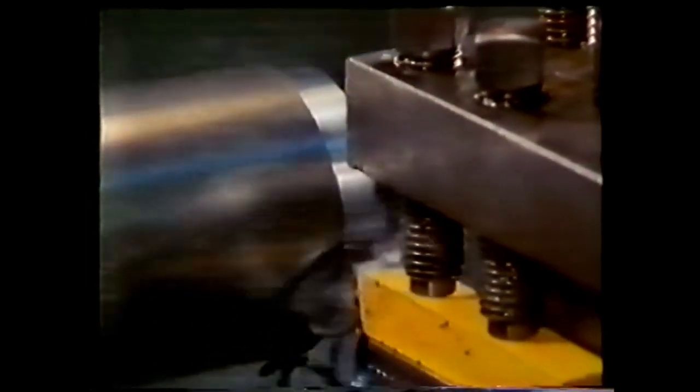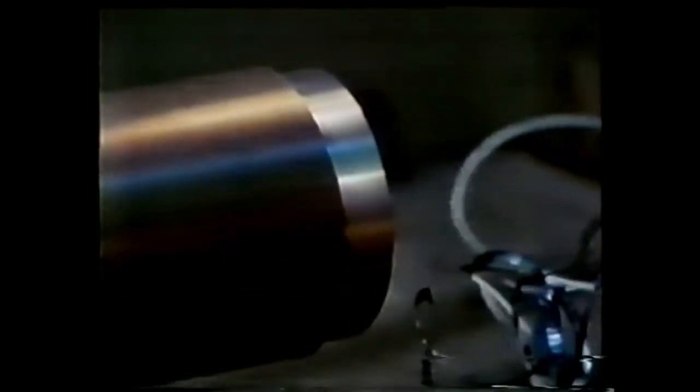The finished twist drills are used with a wide range of metals, and they give a high rate of metal removal. They have the same cutting properties as high-speed steel lathe tools. The lathe tools are ideal for jobbing work. They're also more than adequate for heavy-duty cutting. The drawback with these welded cutting tools is that when the cutting end has to be reground, the tool must be reset before cutting can start again. One way to overcome this is to use high-speed steel inserts.